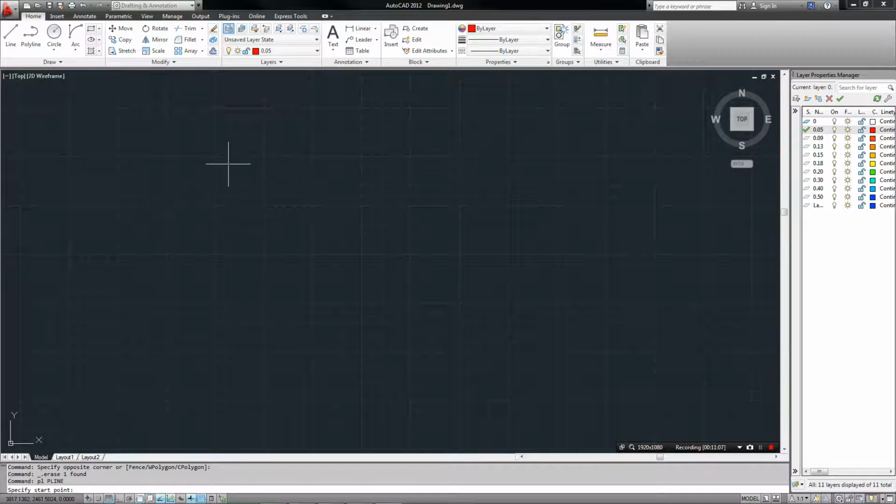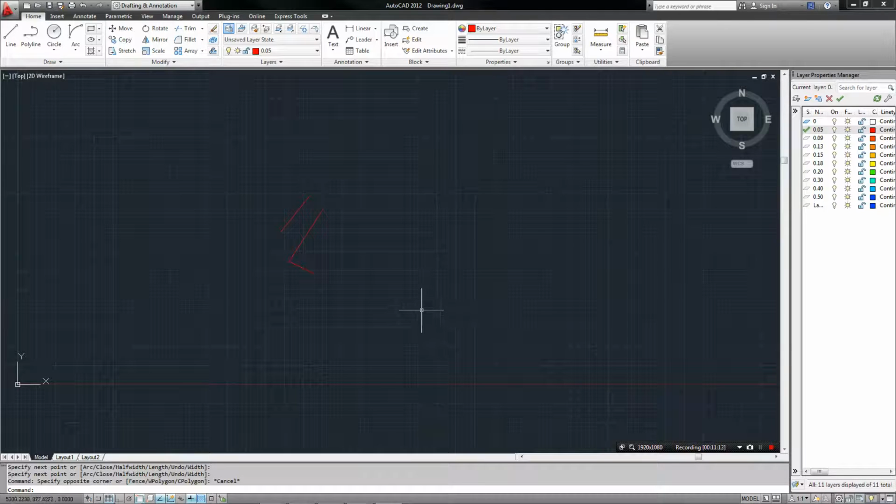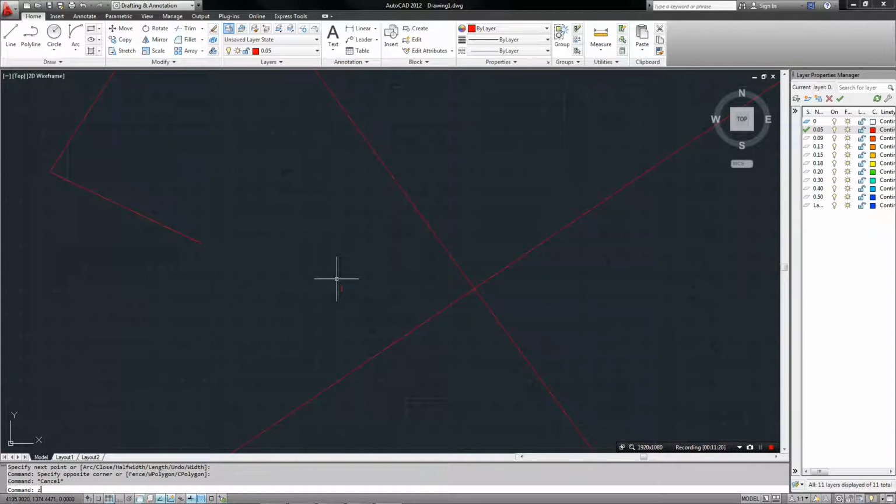Now a few that aren't on there. So zoom extents is a really handy one when you want to find a particular part of your drawing, or if you're a bit lost in your sheet because you've got so much on the page. Sometimes you just press Z space, E space, and it will bring your sheet back out to the full extents of the drawing. So again, if I'm zoomed in all the way and I can't find where I am anymore, Z space, E space, it's brought the entire page back to where we need to be.